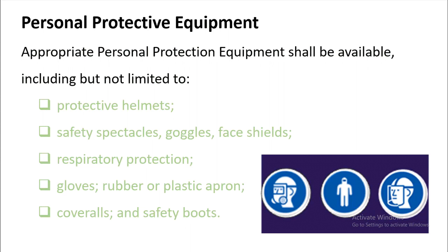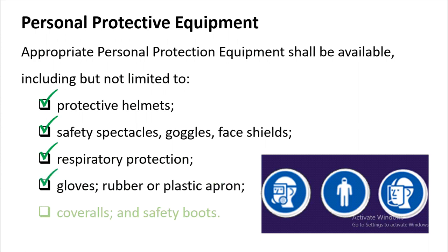Personal protective equipment, as I discussed, make sure that all of your personal protective equipment is appropriate for such kind of hazardous materials. How we can identify the appropriate PPE is through the MSDS. So you can see what the required PPE is in the MSDS while you are handling those chemicals, and use it. As I told you, always consult with the safety department to check the specifications of the PPE that is appropriate for those hazardous materials.